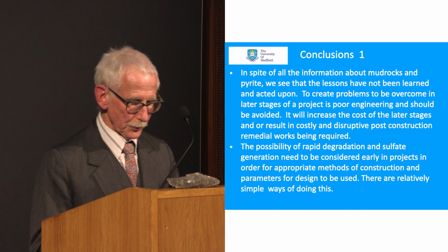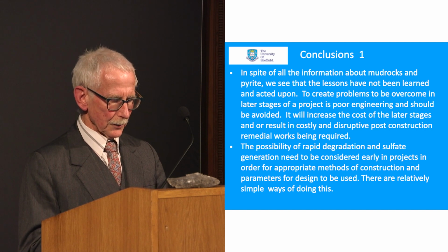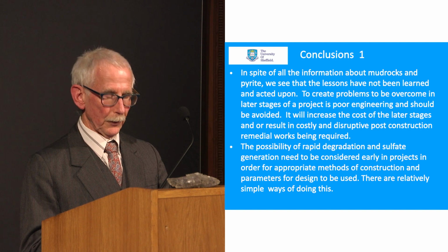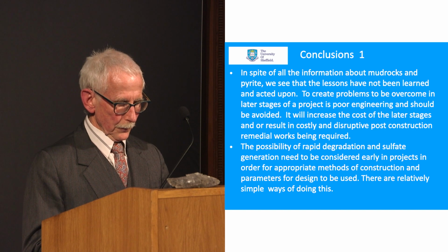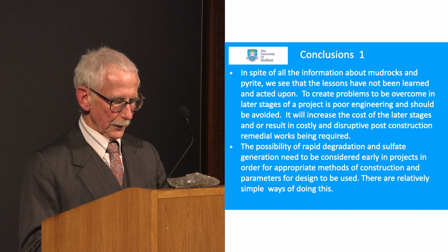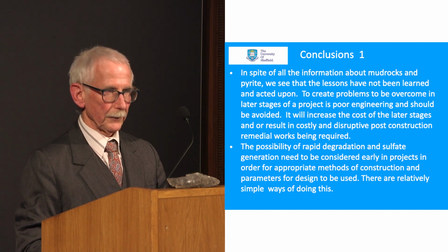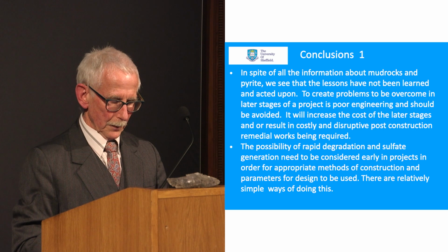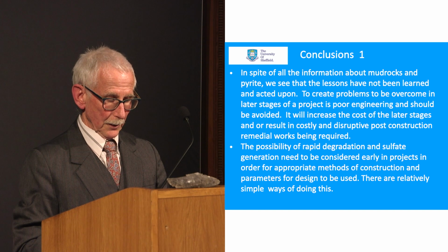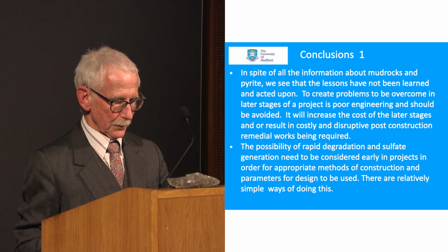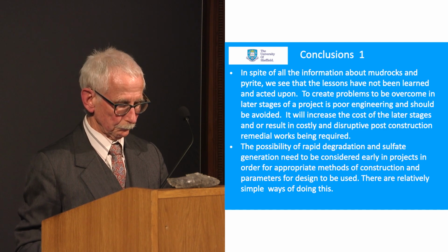I now move to some conclusions. In spite of all the information about mud rocks and pyrite, we see that lessons have not been learned and acted upon in all quarters. To create problems to be overcome in later stages of a project is poor engineering, as seen by these crystals, and the fact that the materials are becoming softened. It will increase the cost of the later stages and or result in costly and disruptive post-construction remedial works being required, as seen in Ireland.